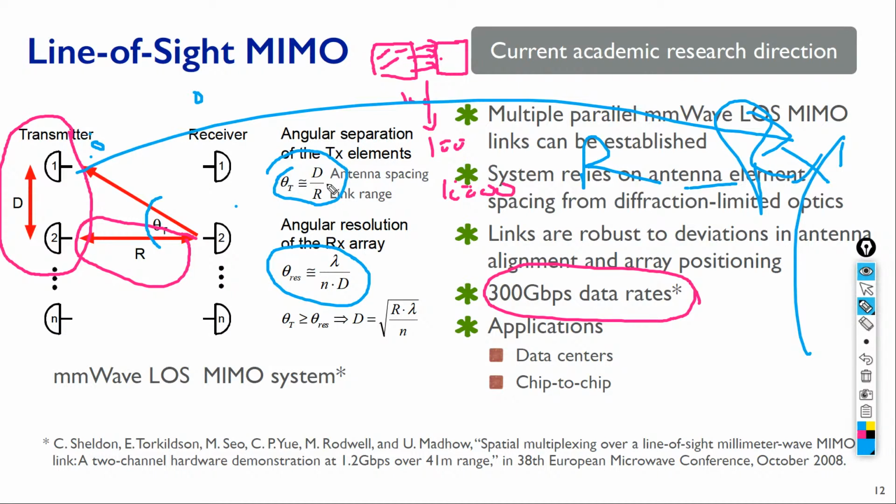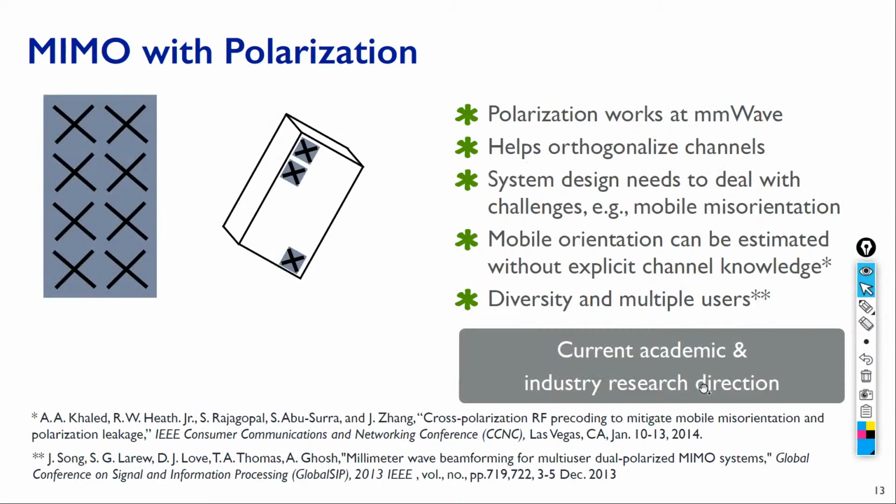So this fact is very important, very crucial, very critical to remember all the time, that fading helps us implement MIMO, make use of MIMO. But when we don't have fading and when we have line of sight scenarios, things become difficult and not feasible to implement. But luckily we found some applications that can be usable. So MIMO with polarization: we said millimeter wave is very sensitive to polarization, and if you are going to use MIMO with millimeter wave, you need to be very careful with this.